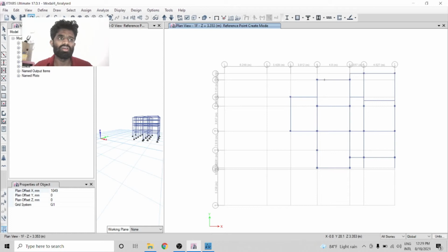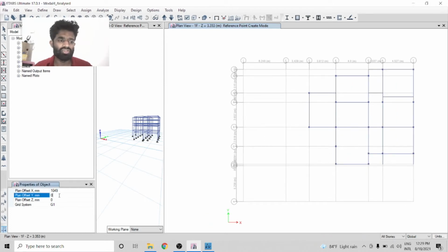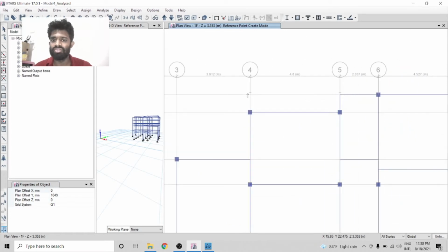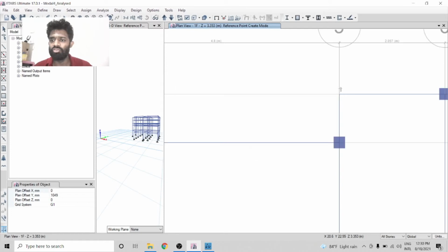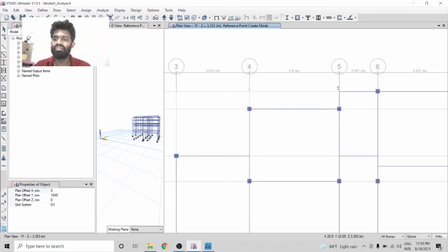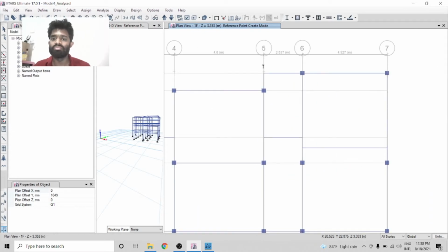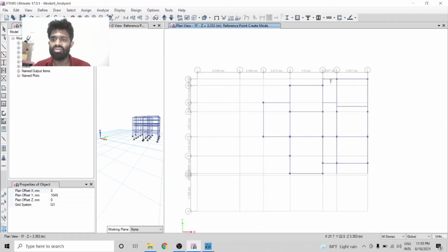No, it's wrong. It's not x direction. It should be in y direction, 1049, and this x value should be 0. So I drew both points. When you draw these points, be careful because you have two different points very close to each other. So be careful. Use the zoom option when you are drawing in this kind of sensitive situation.